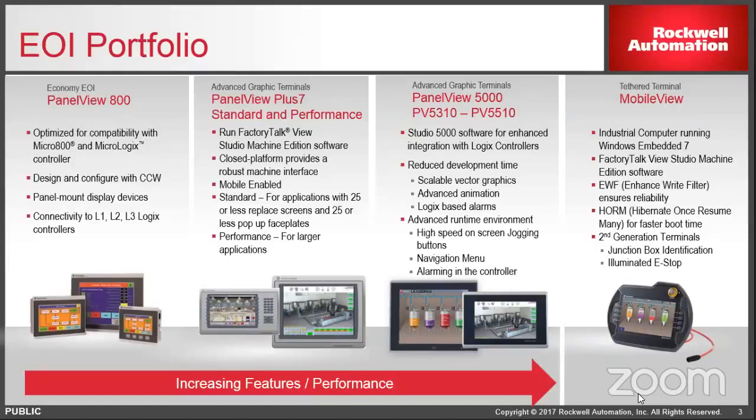Starting off, we call it the component class HMI, the PanelView 800. This is the class of HMI that we use a lot for MicroLogix and CompactLogix L1, L2, and L3 connectivity. And this is programmed in our Connected Components Workbench software. So it's a free software package. It's the same software package to do a lot of things, including your controller programming for the MicroLogix. So I'm not going to talk a ton about that, but if you have any other questions on that, we can talk a little bit later.